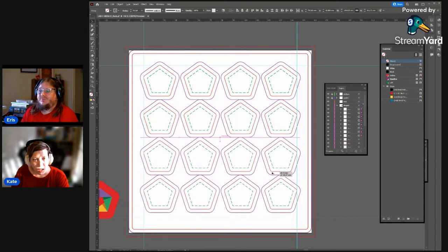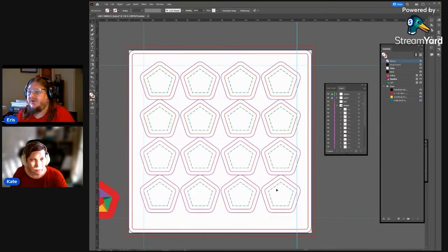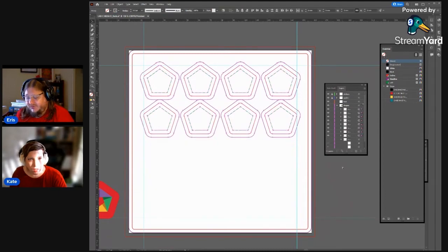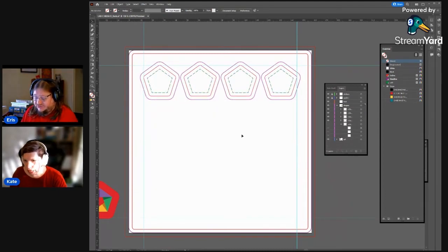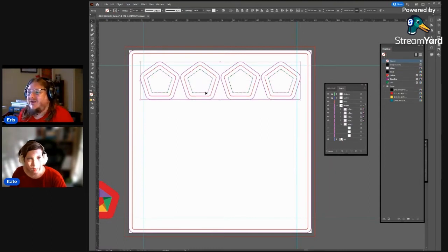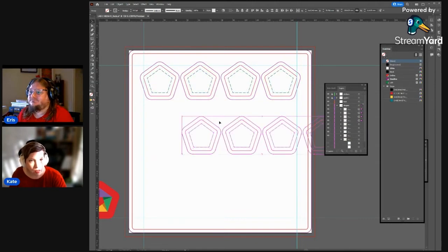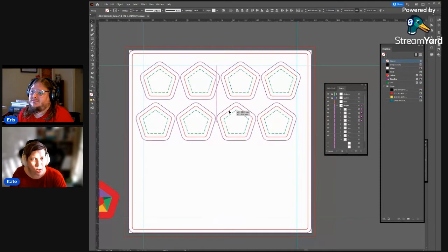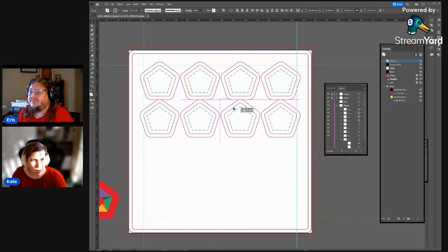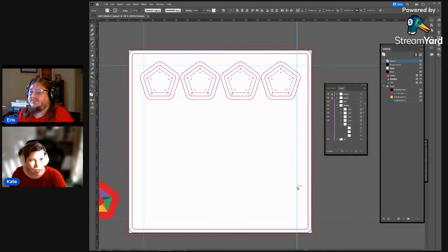So you're just doing duplicates now, for people that don't know at home. When you select objects in Illustrator, if you hold down, well, on a Mac it's the Alt Option key. Is it the Alt key on a Windows? Yeah, this is good having a Windows and a Mac user. If you hold down that key and drag, you can duplicate it much faster than using, say, Control C, Control V, or Command C, Command V. I just copied and pasted, and then you've got to move things around. Anyway, using the Alt and Shift as well